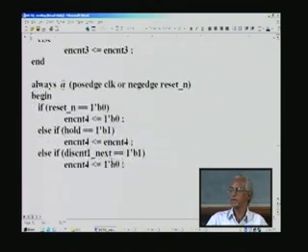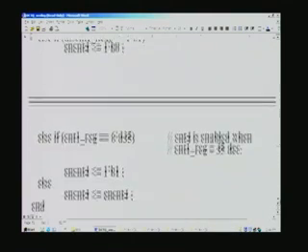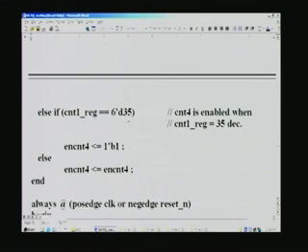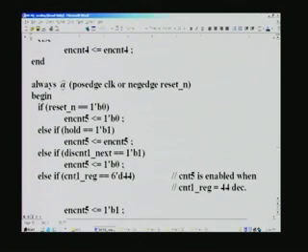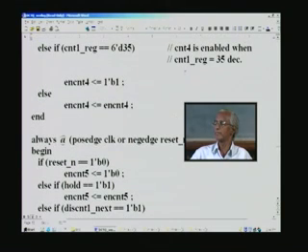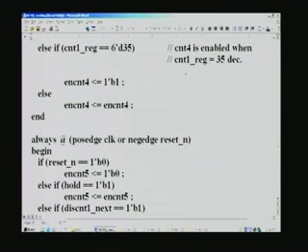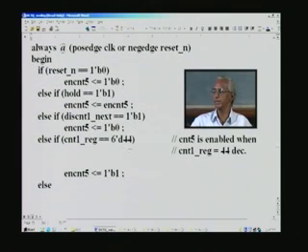And similarly for counter 4 exactly the same, except once again it is a different value here, 35, and for counter 5 this is at the quantization ROM here. So, when the quantization ROM must be enabled is governed by this 35 of counter 1, and similarly when DCTQ must be valid is determined at 44.